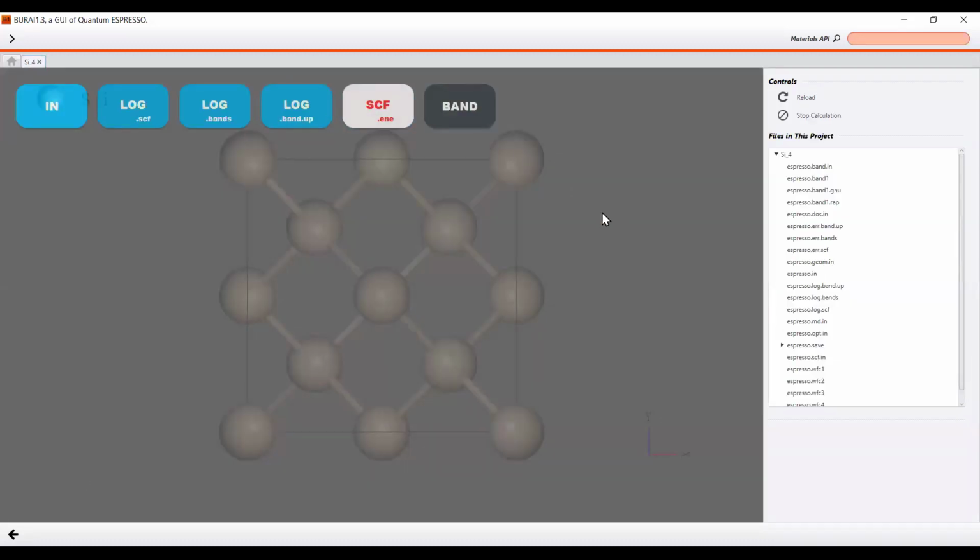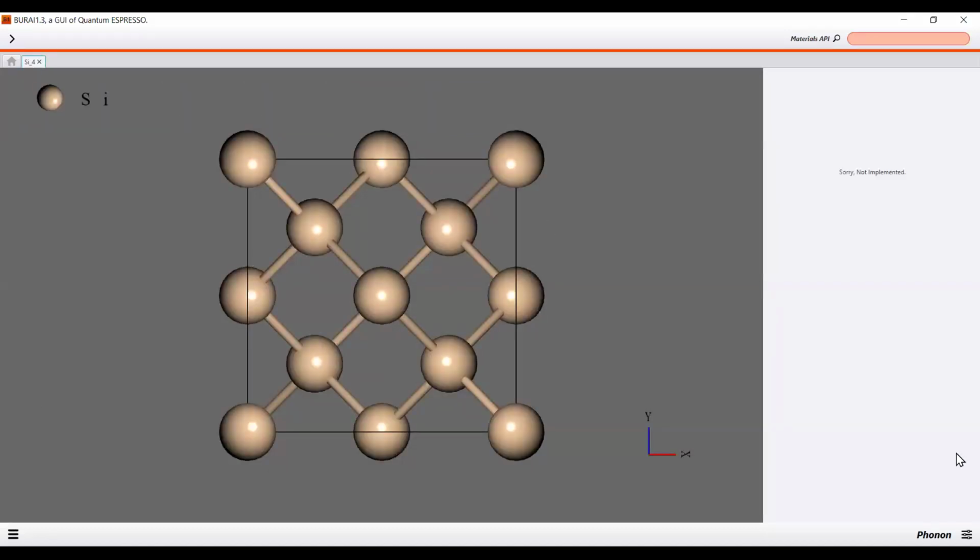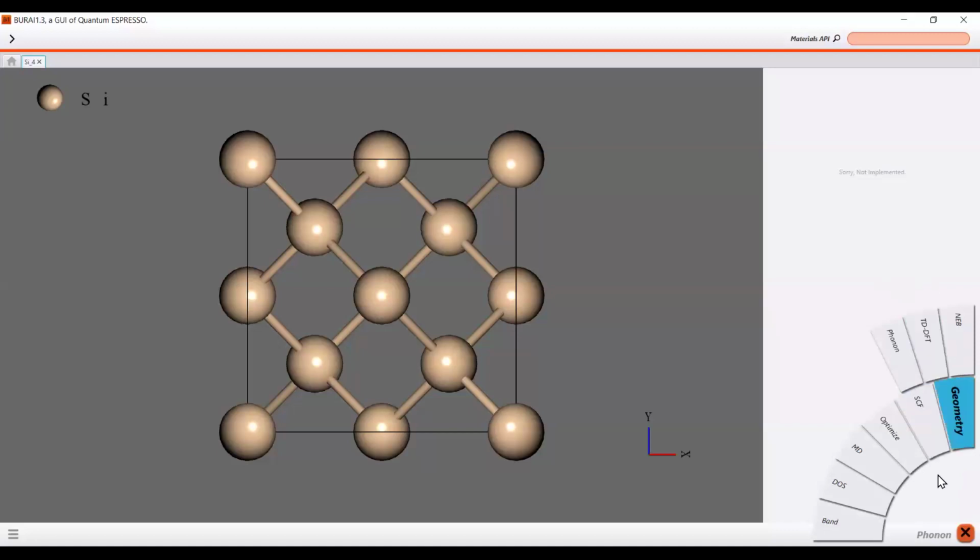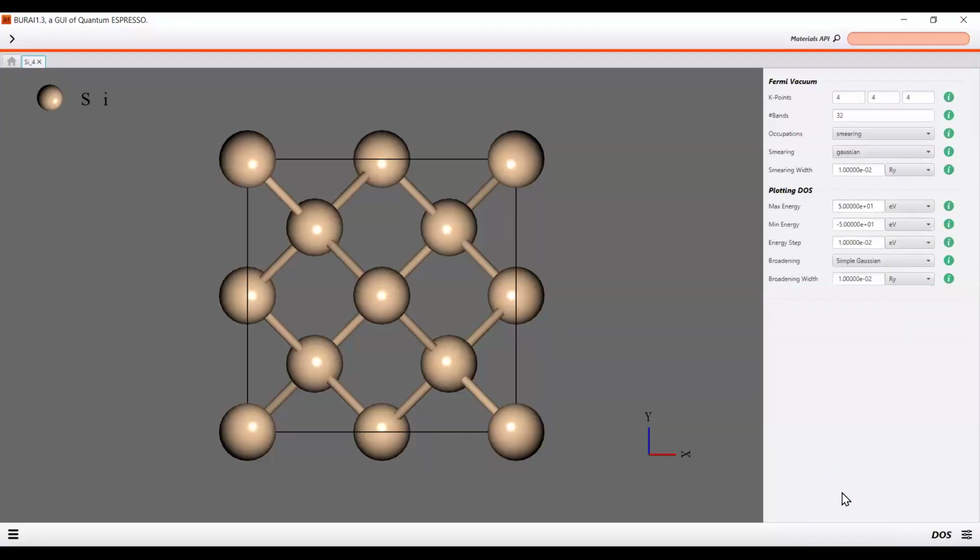Okay, so I think we are moving towards the density of state calculation for this. For density of state, we have to use more dense K points. So here 444 are there, and we can simply put 6 here, because for the density of state, the K points are important. The number of bands is the same as we used for the band structure calculation. Other things should be the same. It cannot be changed.